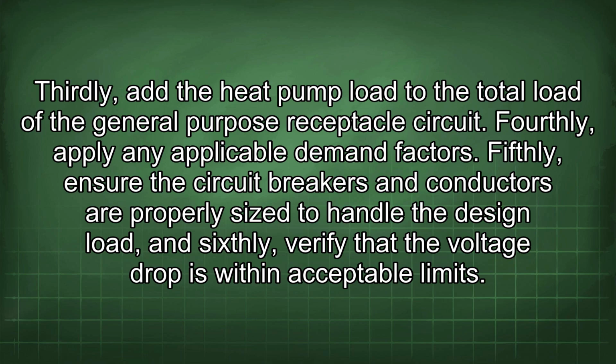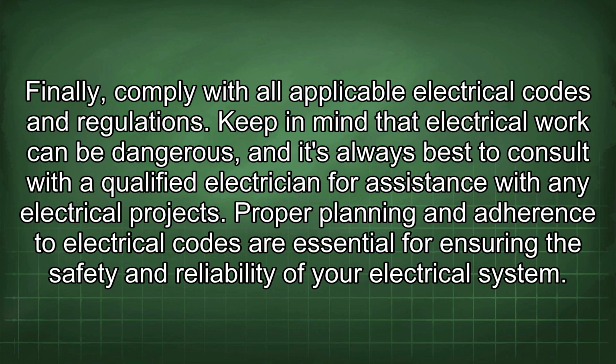Fifthly, ensure the circuit breakers and conductors are properly sized to handle the design load. And sixthly, verify that the voltage drop is within acceptable limits. Finally, comply with all applicable electrical codes and regulations. Keep in mind that electrical work can be dangerous, and it's always best to consult with a qualified electrician for assistance with any electrical projects. Proper planning and adherence to electrical codes are essential for ensuring the safety and reliability of your electrical system.